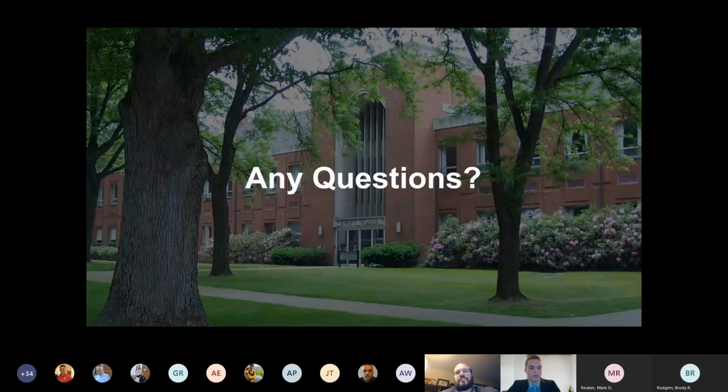Yeah, I can answer that if you guys can hear me. So in the Trane Trace program, we actually just set all the air requirements to ASHRAE minimums because we weren't sure what each space really counted as. So those were just set to the ASHRAE minimum air changes per hour. Obviously, lab rooms and places like the 3D print room would require more, but the 3D print room is actually on its own system right now, so we kind of left that out of our own calculations.